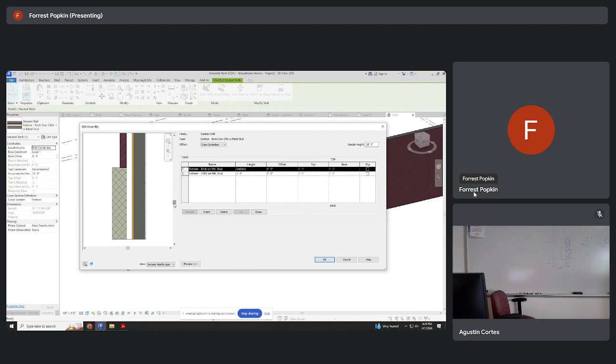So why am I harping on that? Well, let's say I'm an intern or a low-level person who doesn't know what I'm doing, and I built this to go fully in the cavity, and I have no air gap here. Is that a possible way to detail it? The answer is yes, there is. I could make it a detail where I make my CMU bottom completely watertight, I seal it or do something, and I flash from the top, and all the water that gets into my cavity has a weep hole before it gets to the CMU.